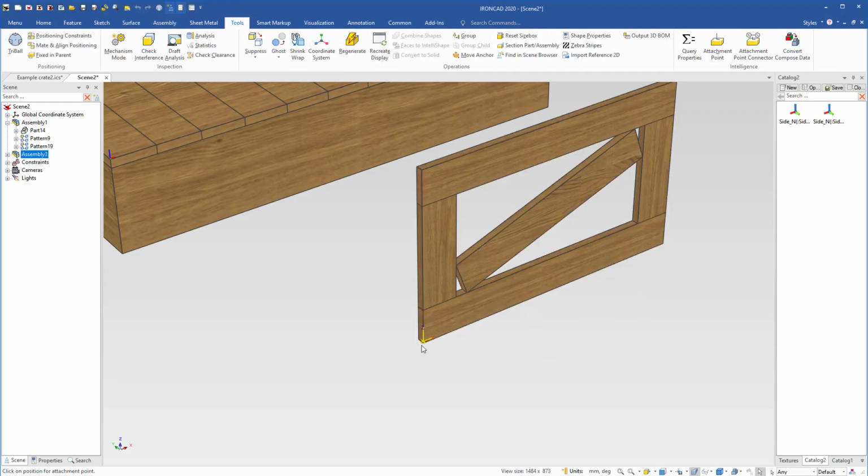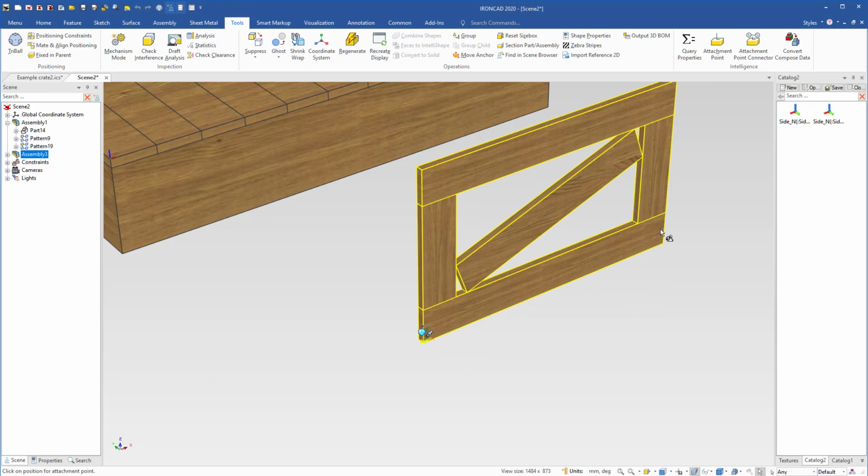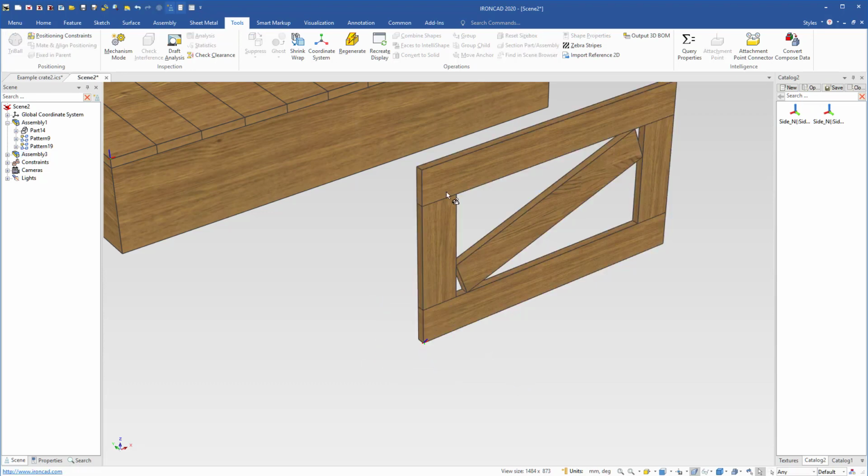We're going to add it down on this point, and now the X is along our length axis, which we want it to align to this red axis up here. And remember, I said it anti-aligns the Z. So right now the Z is up, and if it connects to this one, it's going to be pointing down on the board. So we do need to rotate that. So let's click it, turn on the triball, rotate it down 180 inside there, and we got that thing updated. There we go, pointing down.